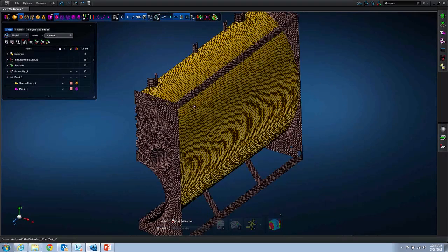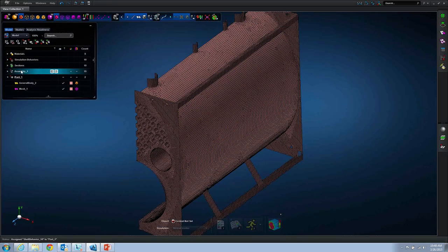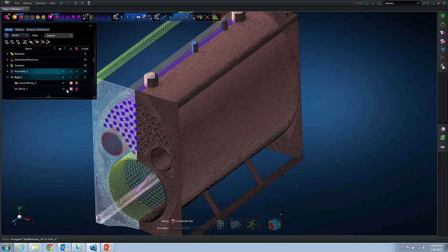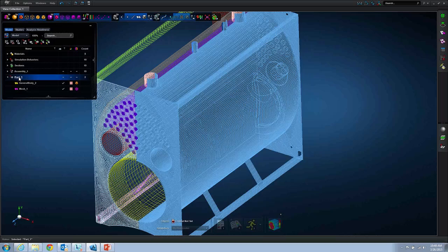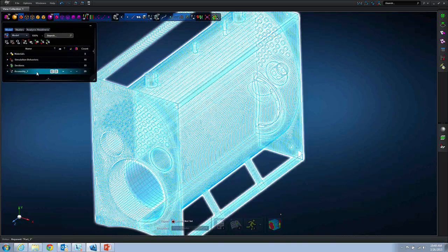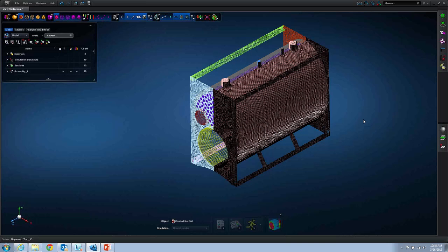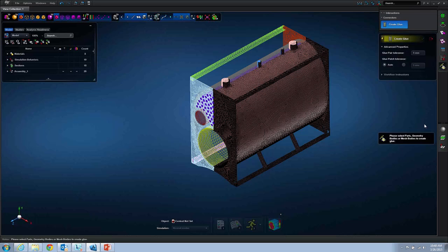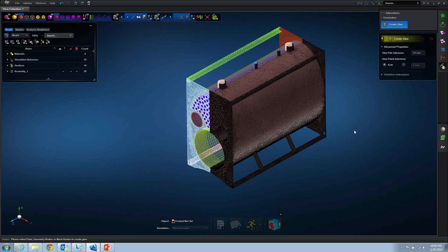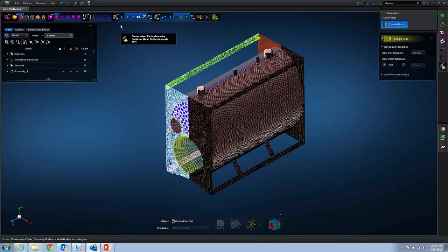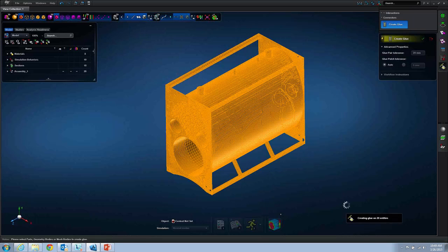Okay, now this is the assembly of the original half, and now I'm going to drag this new part that we created into that assembly. Now we have all of these parts together and everything is disconnected. The last step is glue creation. This model is about 2 meters in size, and I'm going to give about 20 millimeter to find all the glue patches, and I'll continue to use auto tolerance for the glue patch. I'm going to select all the parts in the model.